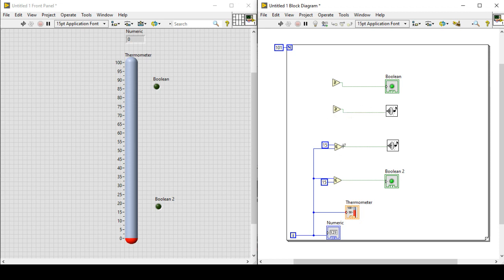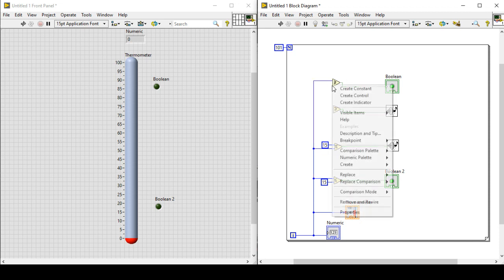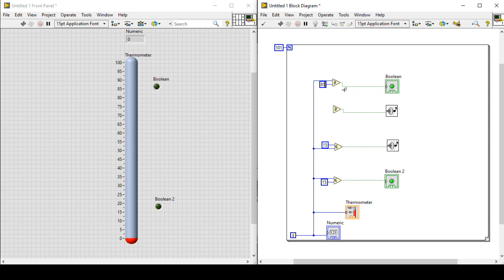Now, the X to the i in the case of the LED comparator, and the constant will be on Y. So again, here we are saying to this comparator that if our i is greater or equal to 85, this should send a signal to turn on the LED. And remember, here is the complete opposite. You send the Y to the i and the X to the constant.